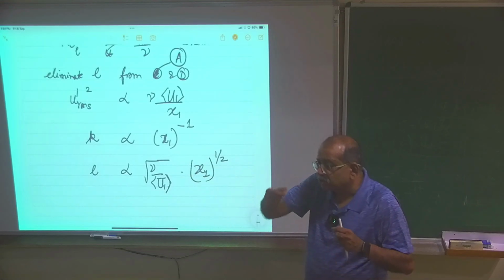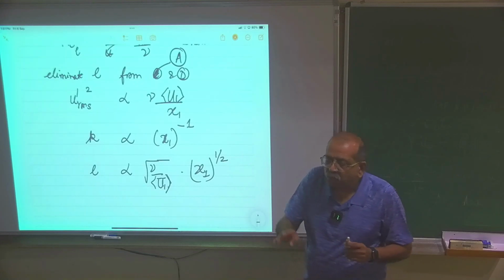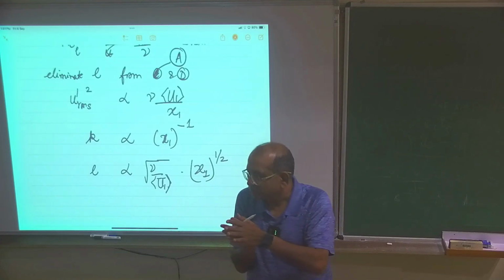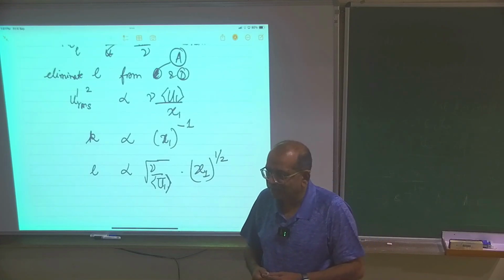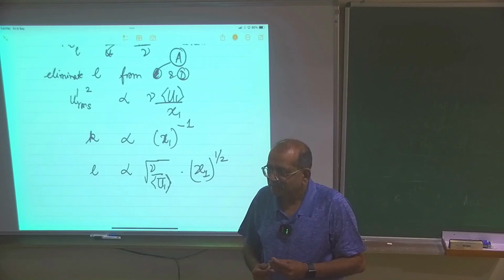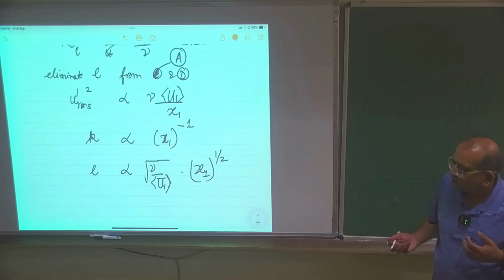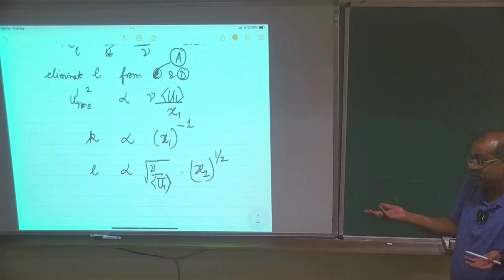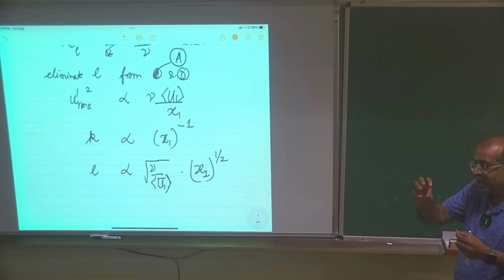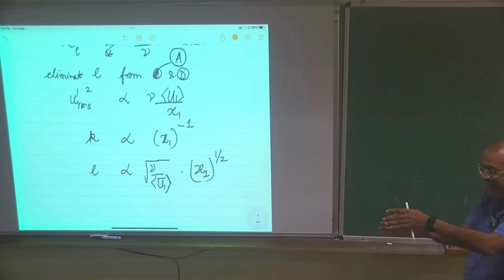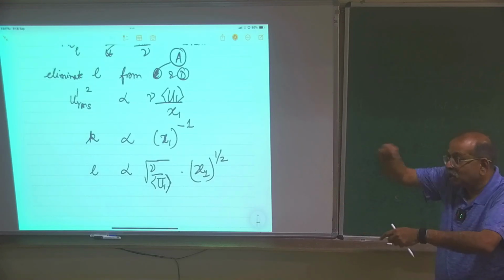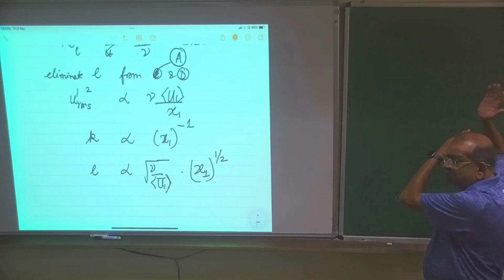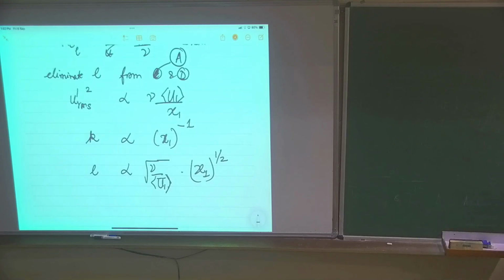See, L is some quantity which you are trying to see. Even though there is no production term, there's a mean velocity going with this, so somewhere that mean velocity is showing its effect on L. I think what possibly happens, again just a conjecture, is we start off with small eddies of the size of the grid, but then, as you rightly said, those eddies get a chance to expand, because now there is nothing like a grid restricting them to the size of M. So initially they tend to expand, but then once dissipation comes, everything decays. That is possibly what is happening.